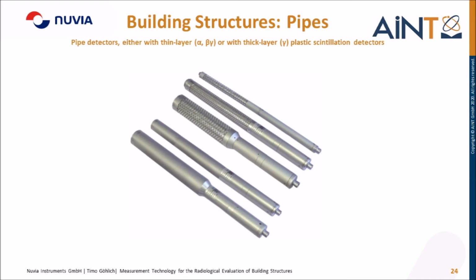These are tube detectors, which can be used to measure contamination within the tubes. We have different versions with different diameters. The upper three are equipped with the thin film plastic scintillation detector and the lower two with a thick film plastic scintillation detector. The upper three are suitable for alpha, beta, gamma, and the lower two for gamma measurements only.